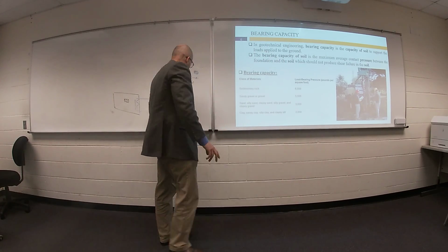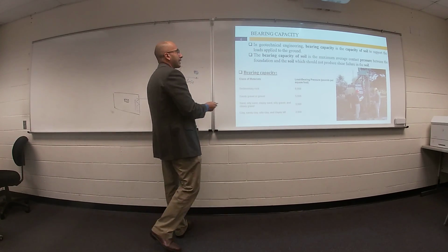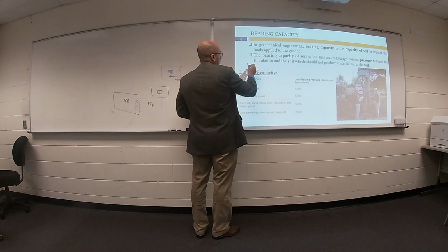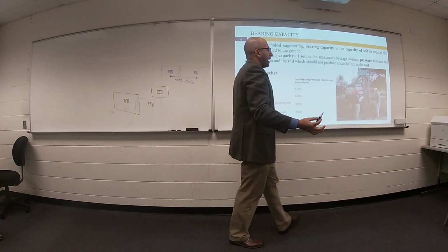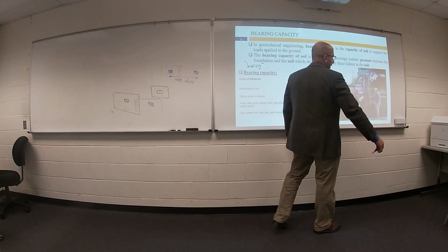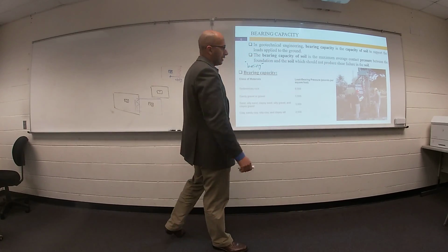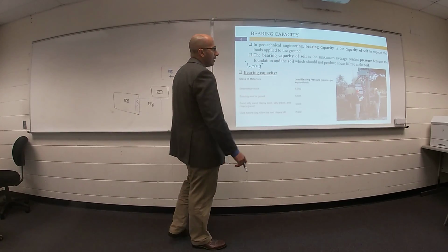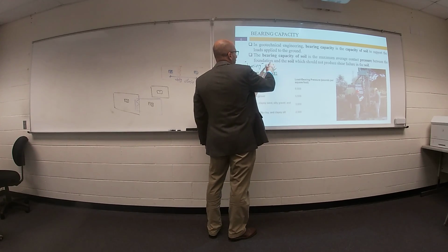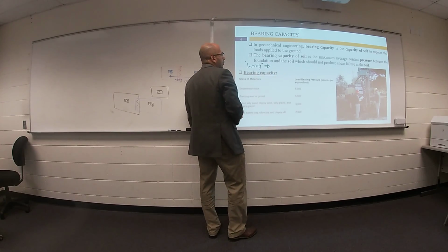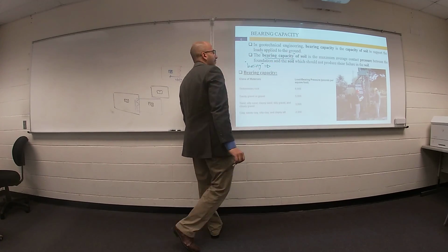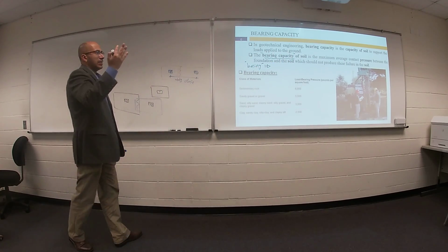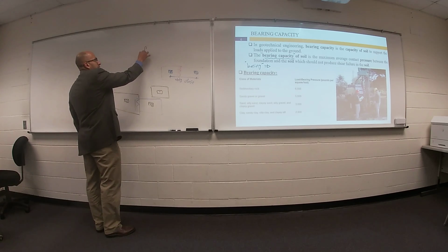We also have something called boring. You can get samples from different depths of layers inside the soil, and based on some lab tests, you can determine something called bearing capacity. Bearing capacity is something like the compressive strength of concrete, f'c.